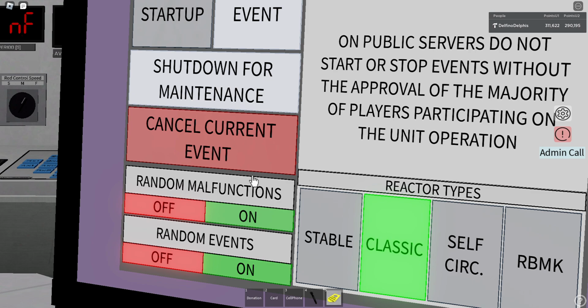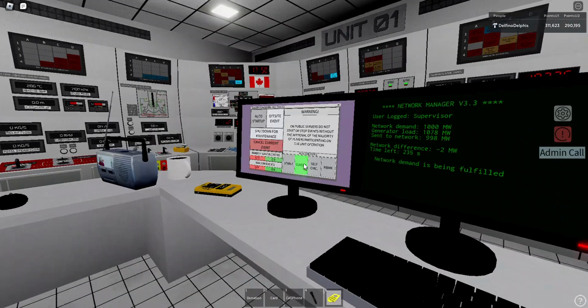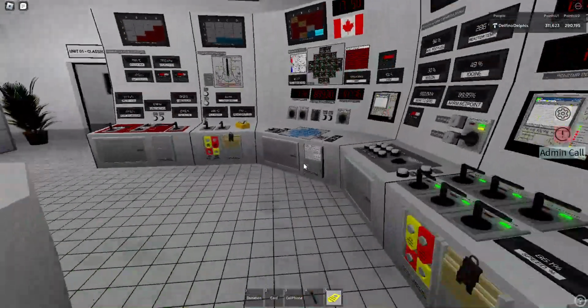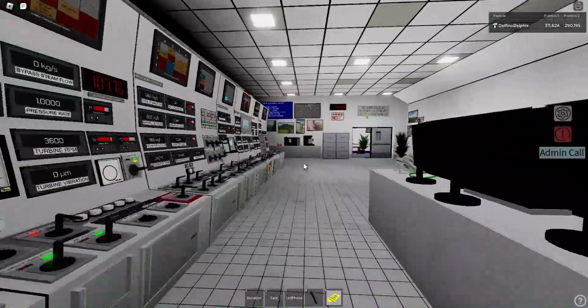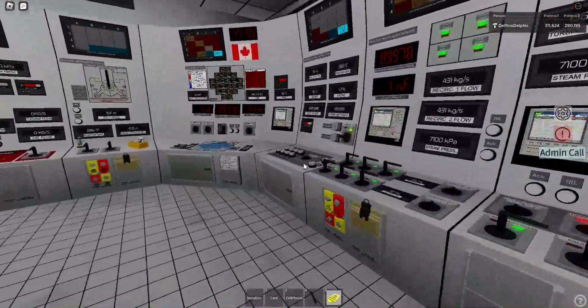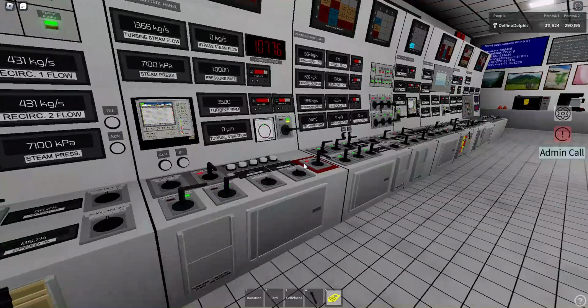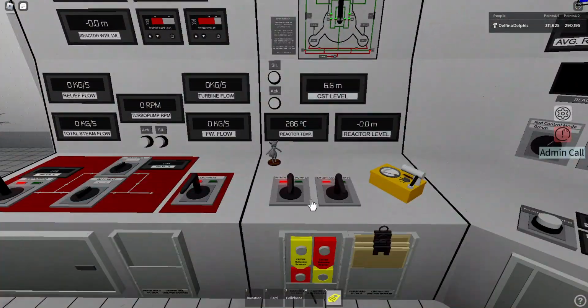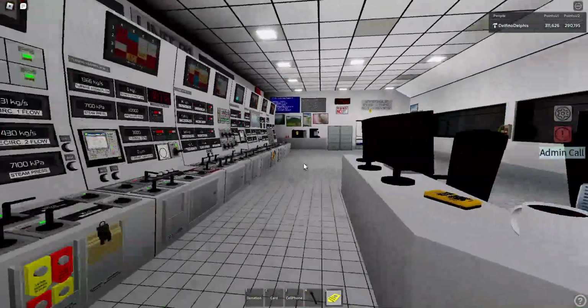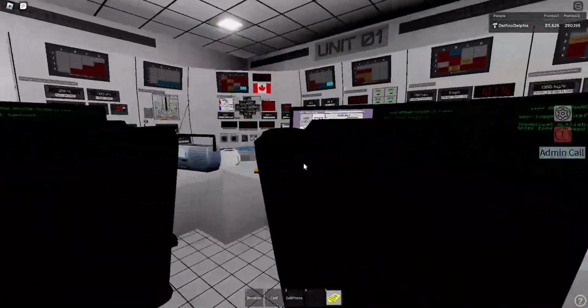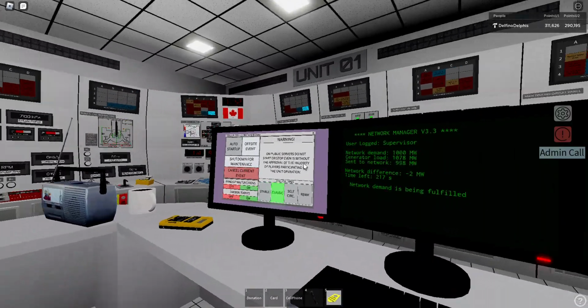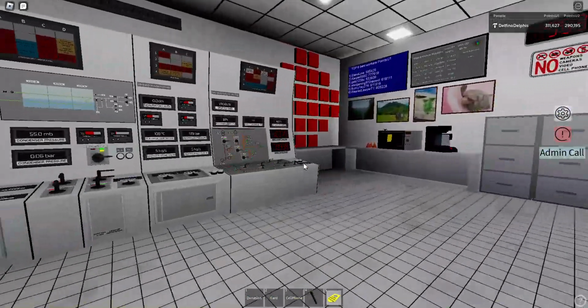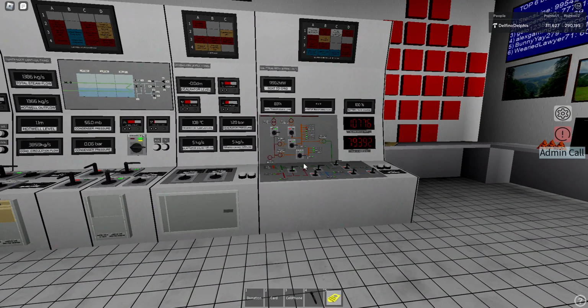And also, some events can happen. One of the events is shutdown for maintenance. You just stop the reactor. I don't want to go into details a lot about it. You can just shut it down, turn off everything and enable the cooling pumps, and you will have to cool it and it's done. And you can also have this offsite event, when you lose offsite power.